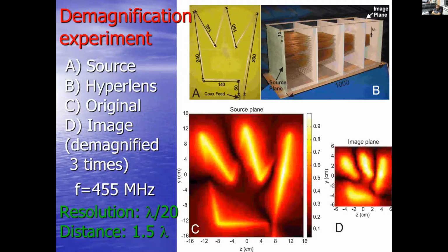Take a look. Yeah, of course you will have temperature noise from the wires. But luckily it will be incoherent. So if you have a coherent signal, then you will be able to detect it at the output. But at the end of the day, I think it's a really good idea. And Misha, we can talk about this a little bit later and design something.